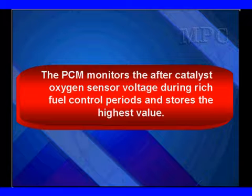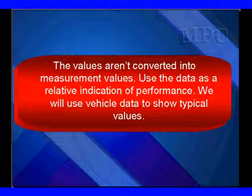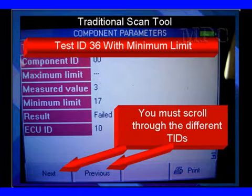The PCM monitors the after catalyst oxygen sensor voltage during rich fuel control periods and stores the highest value. Now, the values aren't converted into measurement values by Chrysler, so use the data as a relative indication of performance. We'll use vehicle data. This is a traditional scan tool. In this particular case, we have a measured value of 3, a minimum value of 17, and we have failed. That means it's not going rich enough.